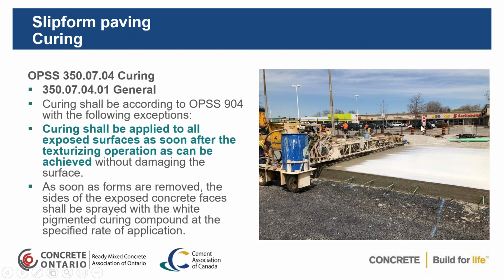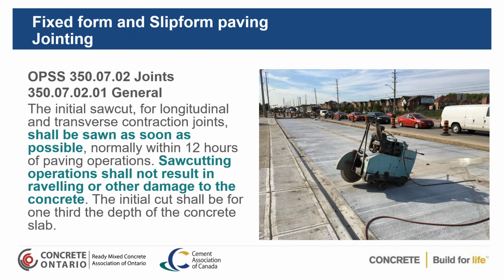And curing, you've got your curing process. They actually have automated systems where they spray the curing compound as soon as your texturing is completed. They've got their tining done. That curing compound is placed to ensure that you keep that moisture in the pavement. Now you notice here that they will have to come back. The guy has those handheld devices that they pump up and they spray the curing compound on the sides of the concrete. Because again, you're going to keep that moisture content in there to get complete hydration of your cement and gain that strength that you're looking for.